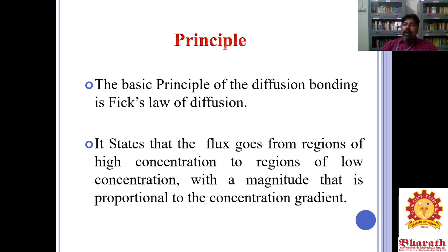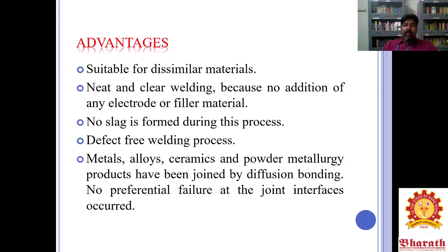So how does it work? It works under the principle of Fick's law. What does it state? Fick's law states that atoms move from the higher concentration region to the lower concentration region. So the atoms diffuse, and we get a good joint. So it is suitable for dissimilar materials, and we get neat and clean welding.